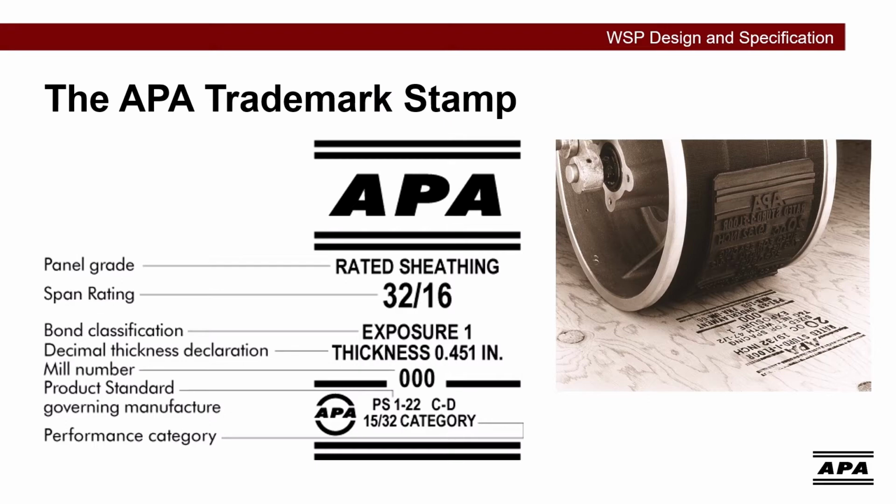Span rating will tell you the recommended maximum on-center spacing between supports when used for roof or floor sheathing for typical residential loading. For example, a span rating of 32/16 means 32 inches on center for roofs and 16 inches on center for floor supports. The bond classification will either be exterior or exposure 1.